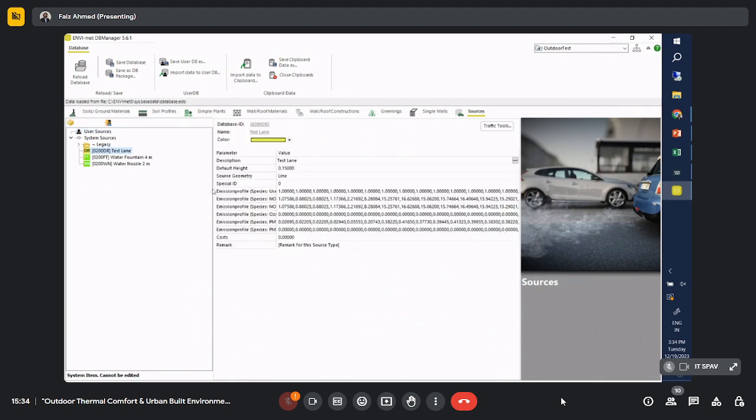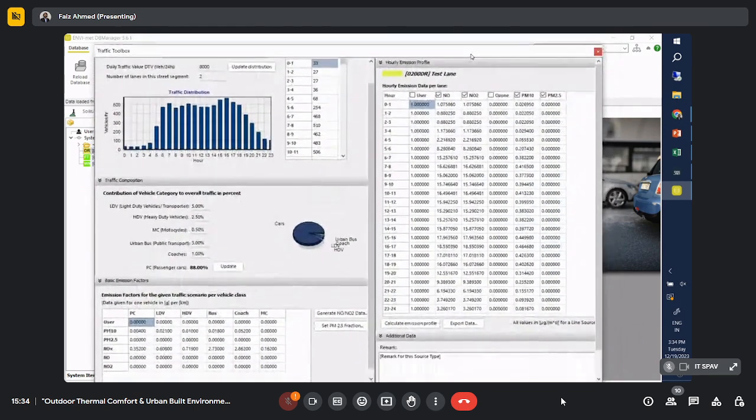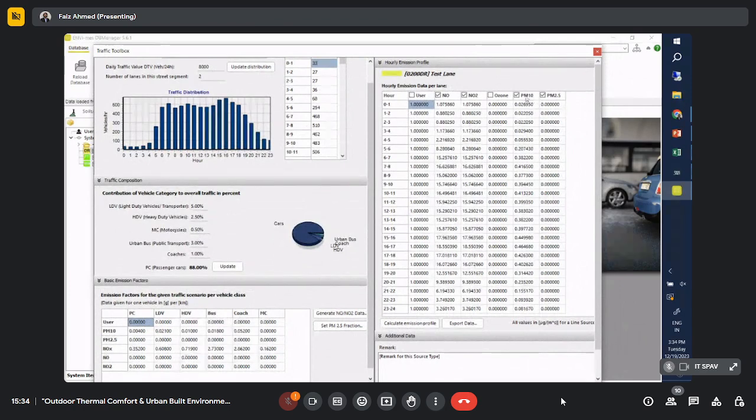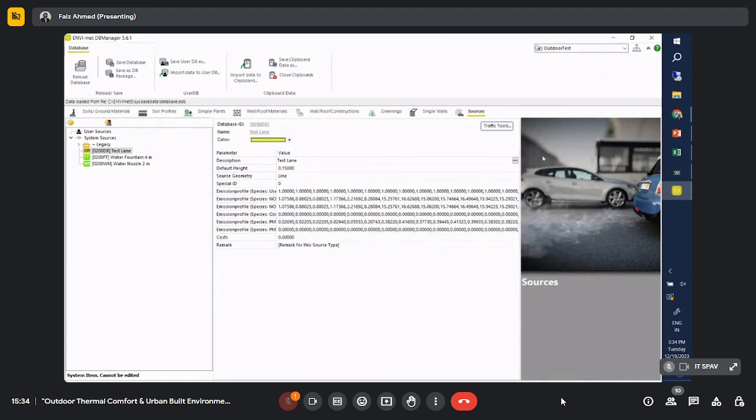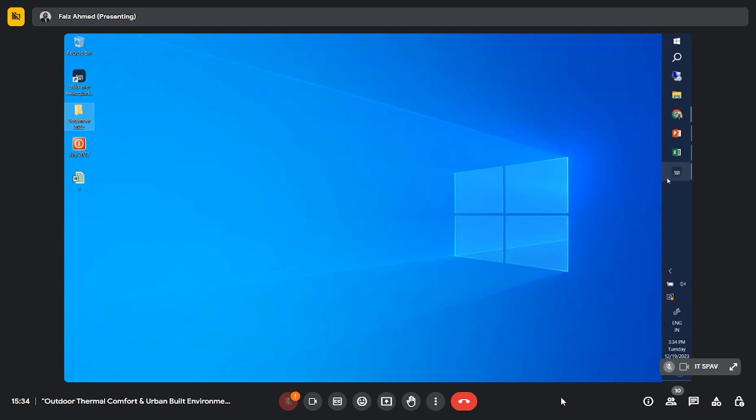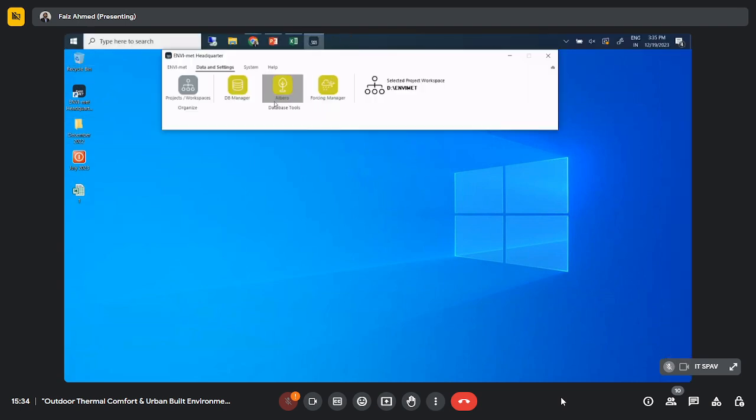And I think in the last session there was some question on how we bring in pollution data. There is a possibility of bringing in very detailed PM2.5, PM10, and all measurements, if you have taken them, as an input for simulating in ENVI-met. So this is one sub tool where we can edit the materials, where we have a material database. The second one is Albero.